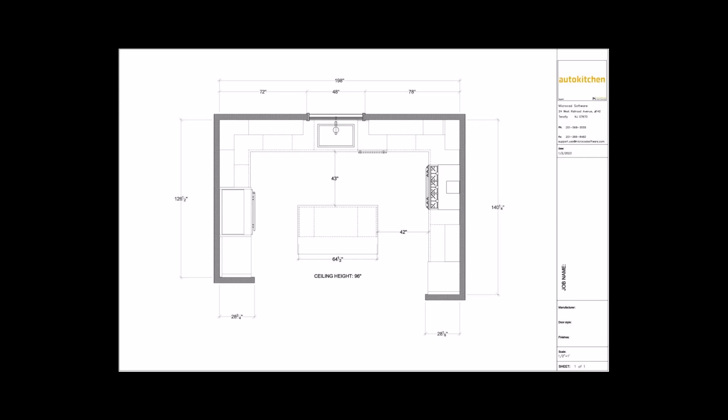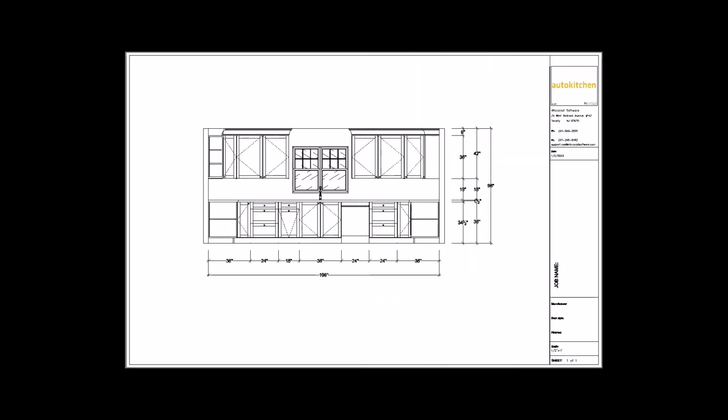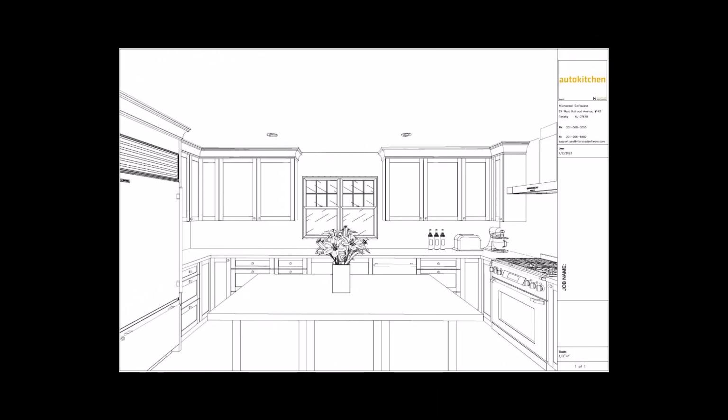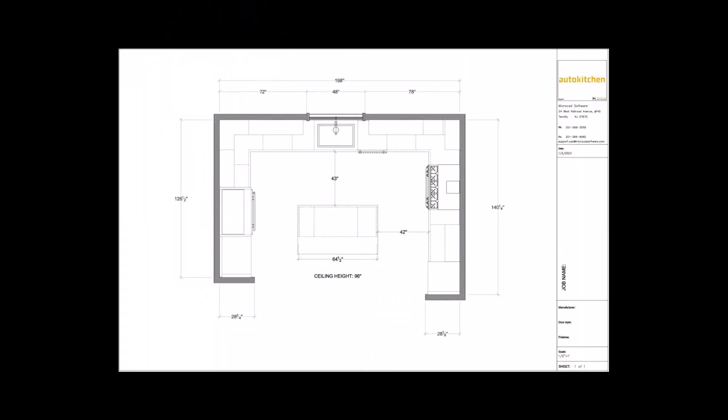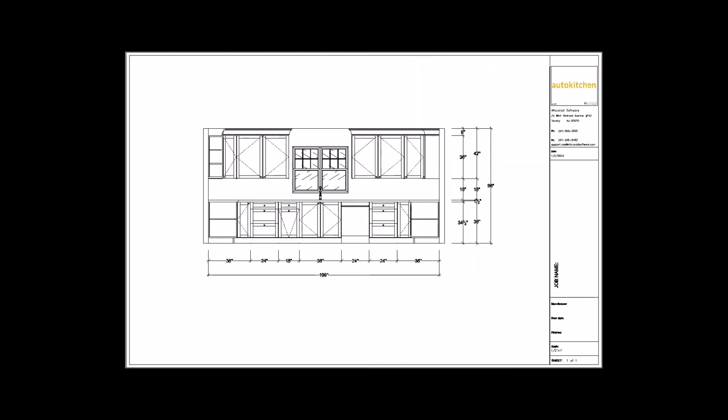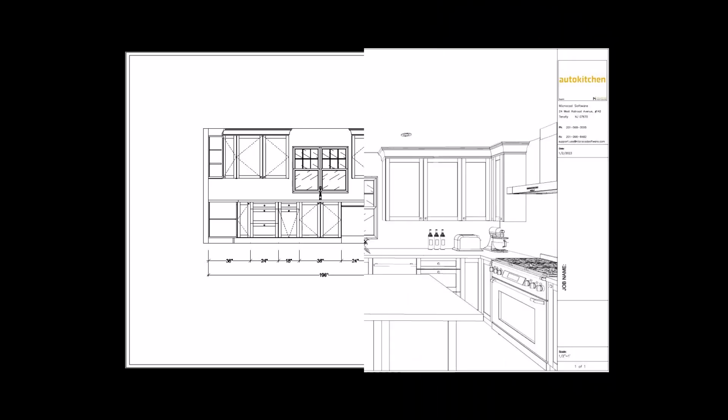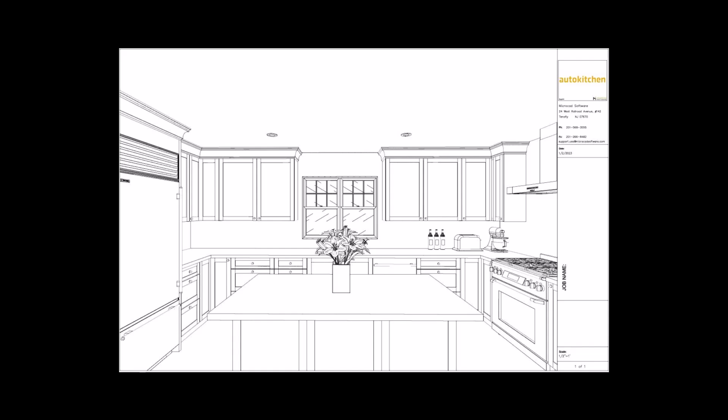To cover printing plans properly, we will distinguish between printing dimensioned elevations and printing all other plans, floor plans and perspectives. The reason for this distinction is that floor plans and perspectives can be printed based on the view on the screen. Dimensioned elevations are printed based on a previously saved view, and this view typically is not on the screen when printing. The above distinction will become clearer in a few moments.